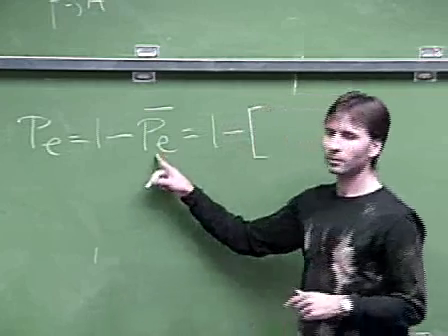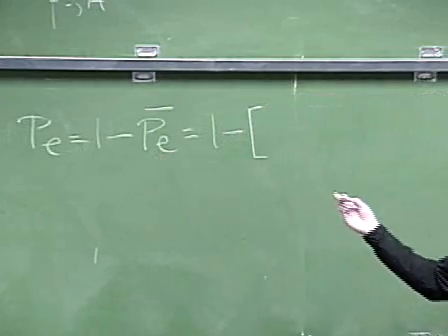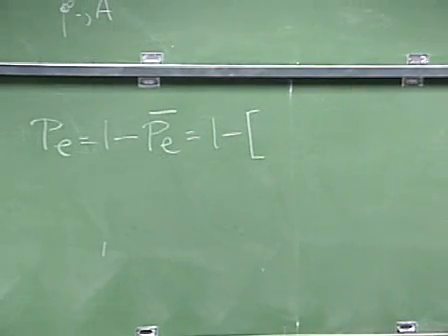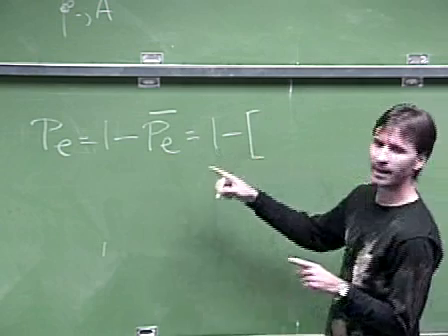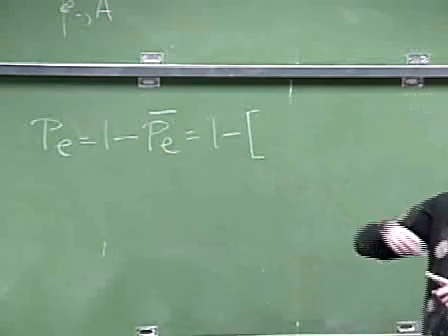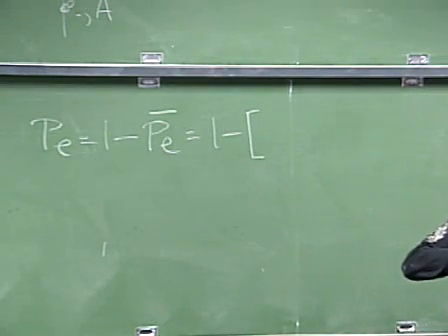Okay, so in order to have no error in the QPSK, what do we need to have on the two BPSKs that compose it? Right? We need to have simultaneously what? Can we have an error in one of them? No, we have to have no errors in both of them, right? So we need to have no errors in I and no errors in Q. Now, we just said that these are independent, right? So we can multiply out the probabilities, right?